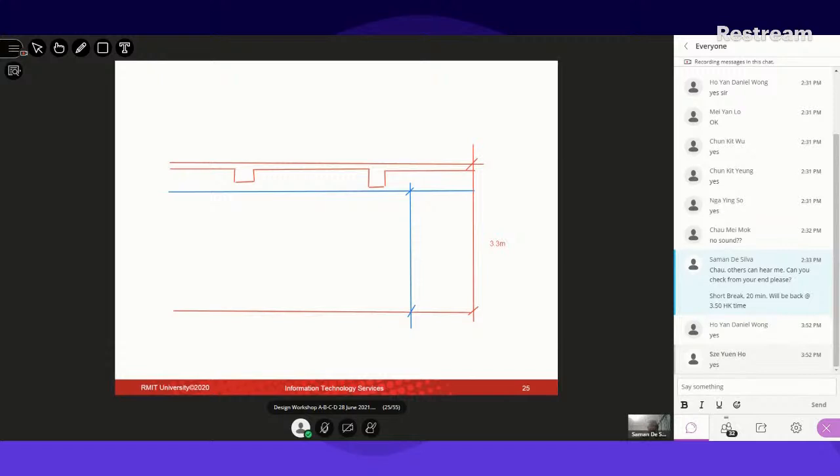your living areas relatively bigger. So the question mark is, what is this value? It depends on lots of things. If you want to have a really clear space and as high as possible, you have to optimize this floor slab design as much as possible so the overall floor depth is good. On top of that, you will have another gap of at least about 300 millimeters or so to ensure that any services are run. So that would determine what this value is.